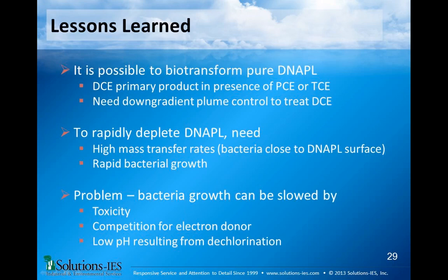One thing to note, we just weren't very smart and didn't do our calculations right. We didn't add enough magnesium hydroxide in this column. By about 300 days, we were doing a mass balance on magnesium, and like 99% of the magnesium we added was flushed out of the column by about 300 days, or maybe 250. You can see here in the MH5 column, we maintained a nice neutral pH until about 250 days, and then we get a pretty abrupt drop. Basically, we had depleted all the magnesium hydroxide by this point, and the pH dropped.